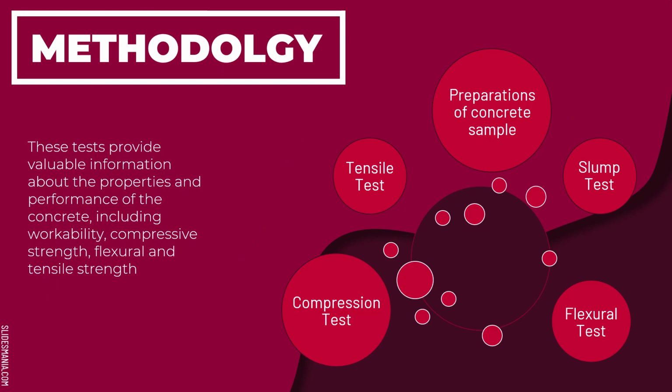Methodology. Firstly, preparation of concrete sample. Then, slump test. Third, compression test. Next, tensile test. And lastly, flexural test. These tests provide valuable information about the properties and performance of the concrete, including workability, compressive strength, flexural and tensile strength.